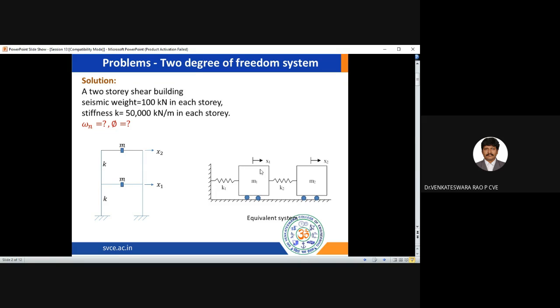We already saw yesterday, last class, that stiffness comes from the column. This is a fixed one, so let us take this. I have considered it in a horizontal manner. You can see that. So the fixed end, then the stiffness is there. The spring I have taken is K1, which is nothing but K here, because both the stiffnesses are the same. Then I have the mass M1, first floor mass M1. Then next one we have another column, the first floor column.